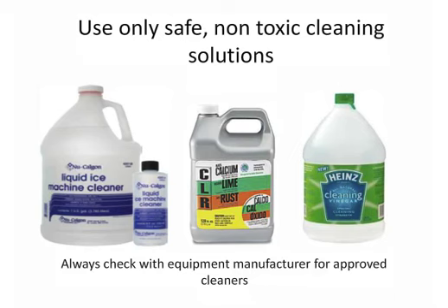CLR, a lot of people use that. Again, that's something that's non-toxic that you can run through there. A lot of contractors actually use ice machine cleaner, because if you think about it, ice is typically consumed. It's a potable fluid application, so liquid ice machine cleaner. Again, always make sure that you're touching base with the manufacturer to make sure it's appropriate for the material you're flushing it through. So ice machine cleaner is typically a pretty good choice.